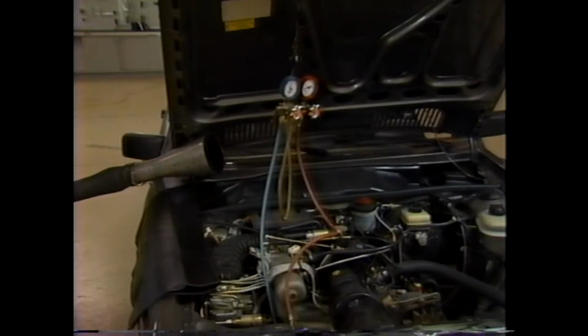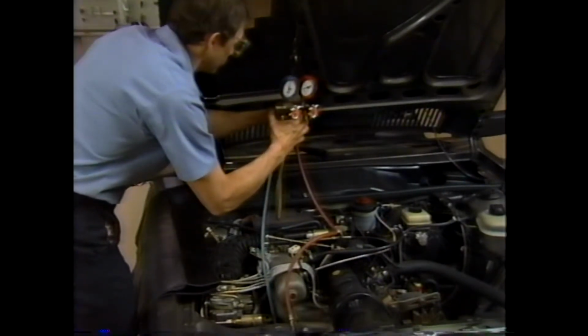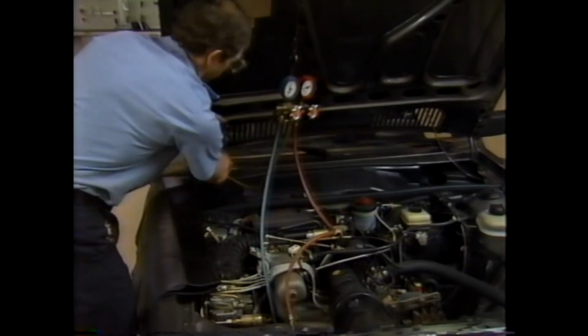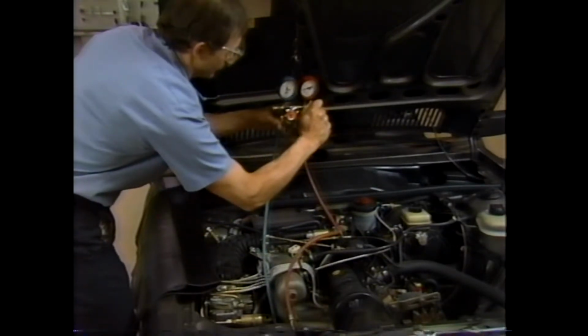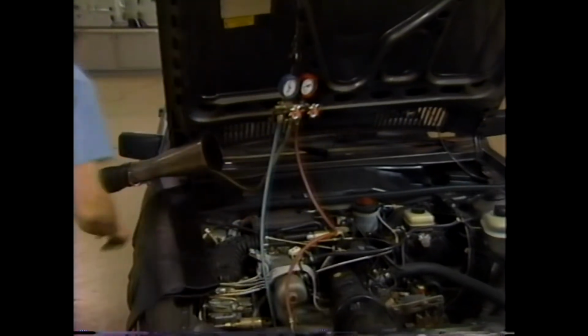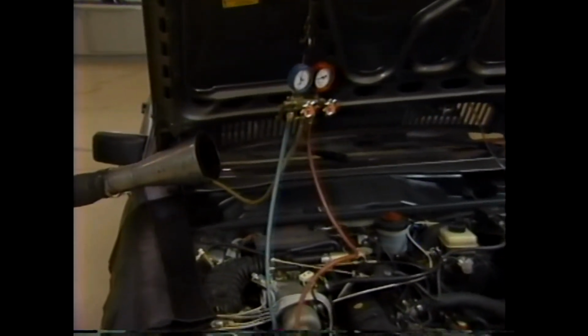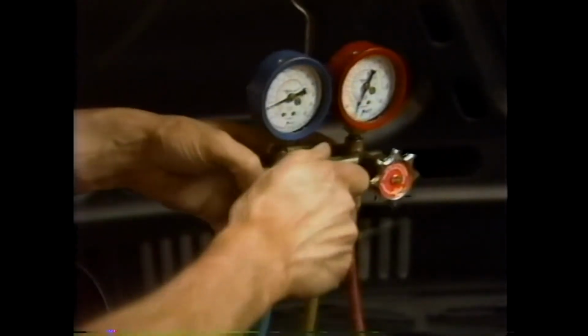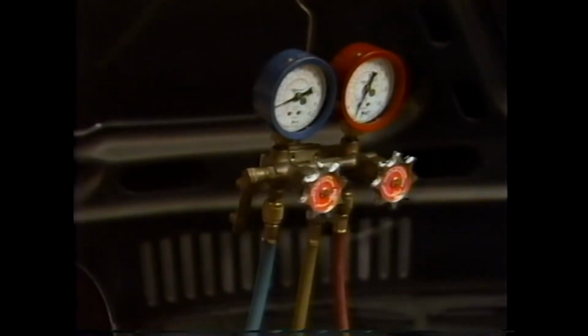Some repairs or component replacement may require the system to be discharged, evacuated, and recharged after you have completed the work. In the final part of the program, we're going to see how to perform these operations. With both gauges connected and the valves closed, the best way of discharging the R12 gas is to let the center hose vent through the shop exhaust system. Then slowly open the high side valve to start purging the system. When most of the refrigerant is purged, open the low side valve to complete the discharge process.